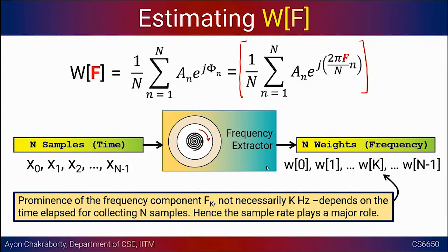But often the data that you have collected could be for, let's say, 57 seconds, right? In that case, you have to do some kind of processing on the data, or some manipulation of this particular value k. It has to be scaled and multiplied and so on. We will come to that quickly, right? But just remember that it's not always k hertz, right?